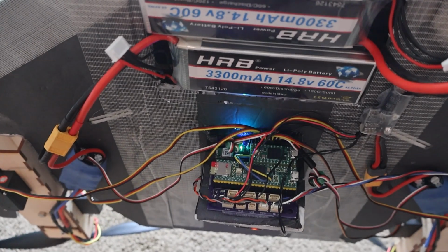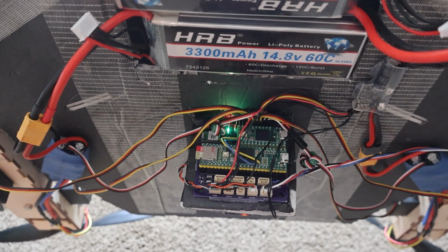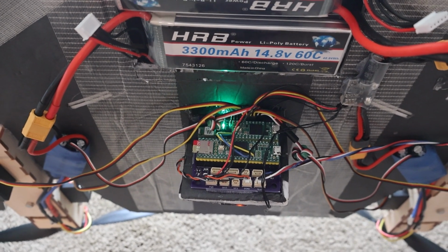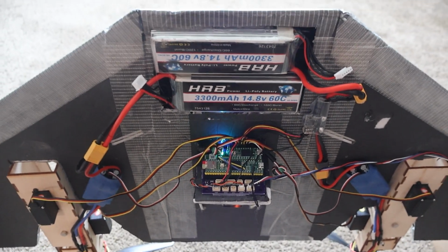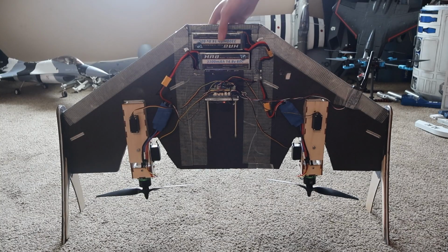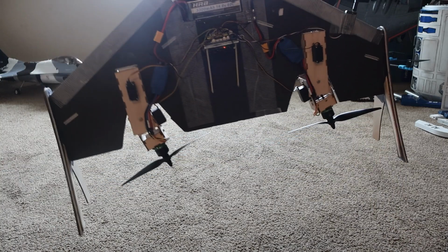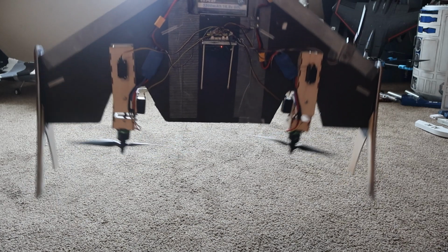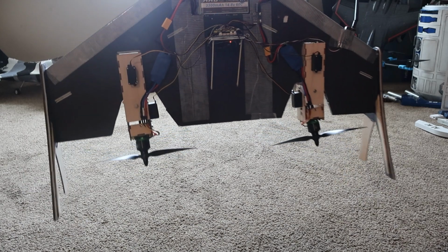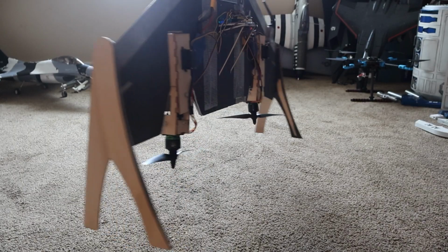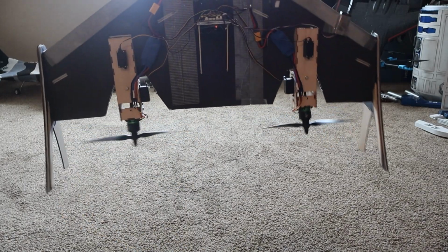This setup isn't very pretty, but I was pretty much running out of time, so I was just focusing on getting something to work rather than focusing on aesthetics. Here's a basic hardware test, just to verify everything's working as expected. I'm also checking for control deflections and directions. This only has proportional gains applied currently just to make this process a little easier.